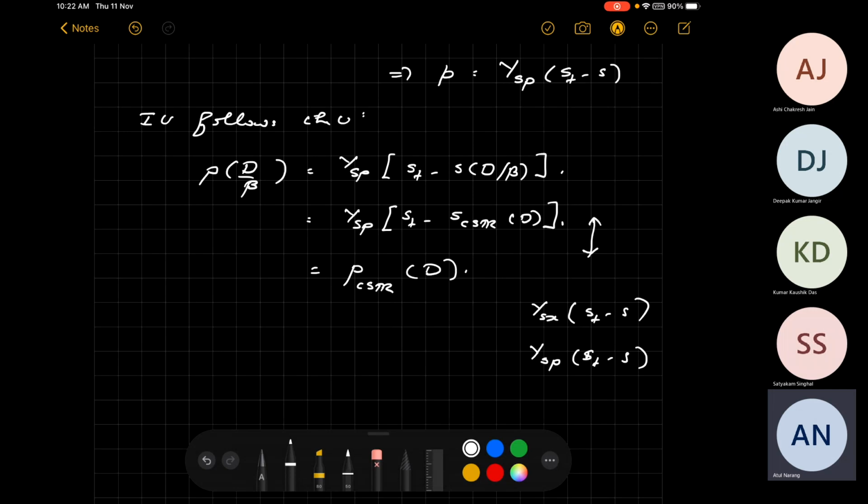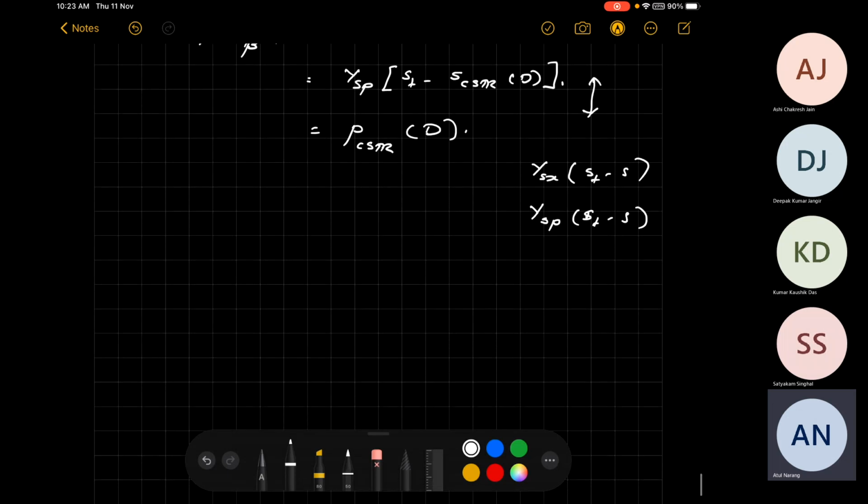I mean, both the product and biomass are products in a single reaction. So if the biomass concentration is given by Y_SX multiplied by (S_F minus S), you shouldn't be surprised that the product concentration will have formally the same structure. You can just work it out by going back to the Monod model. I may not have covered this in the exact formula, but you have the same idea. Do you follow my point?